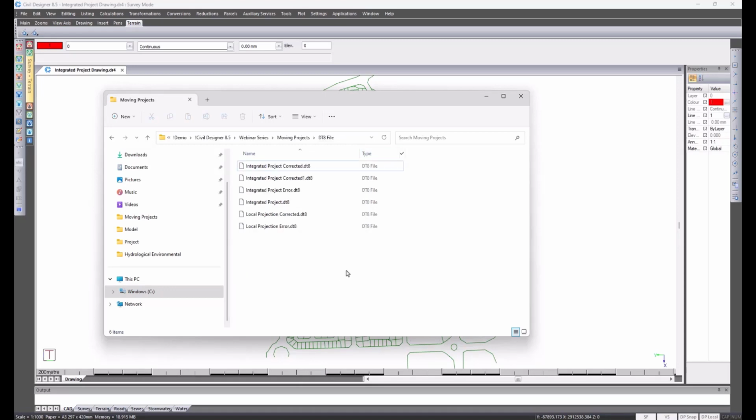Now, if you recall, when I started with this, I've said that the roads are associated with the terrain file, but we are going to import new terrain data. So what I'm going to do here is delete this and create a new one. And this is so that we don't have to rename all 35 roads.